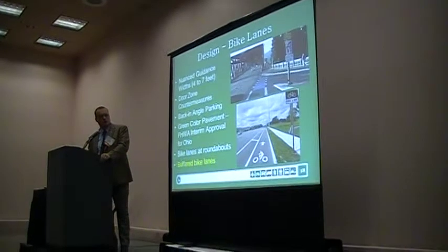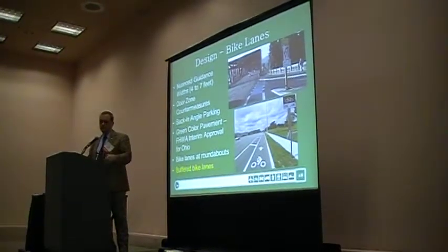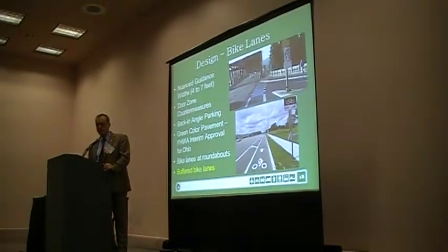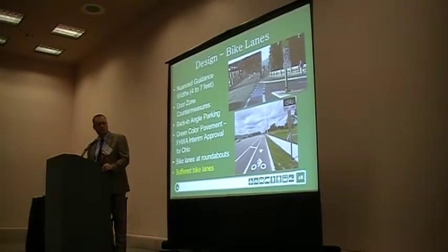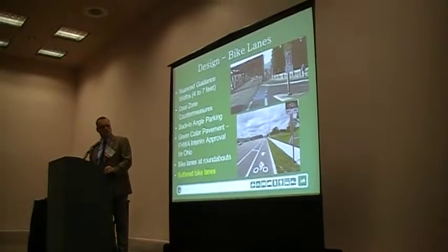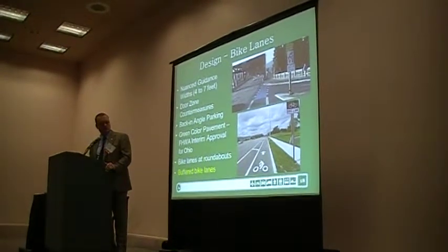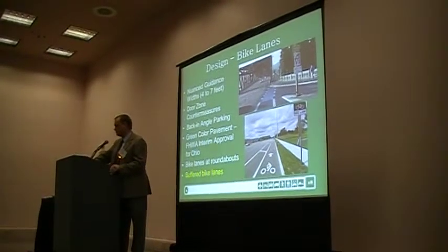The door zone, again, providing enough width from the door zone. Sort of the trade-off when you're trying to retrofit, that you have to consider the likelihood of something happening. Green colored pavement, as mentioned, currently in Ohio, Federal Highways approved it for interim use and experimentation.